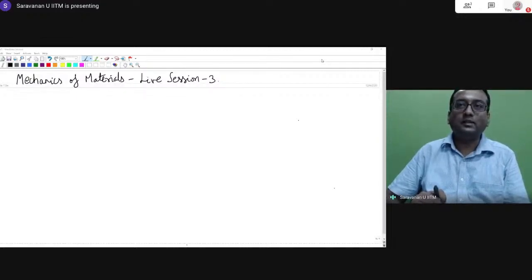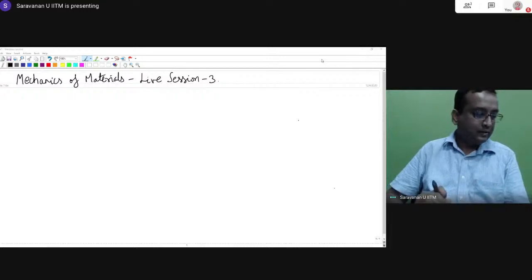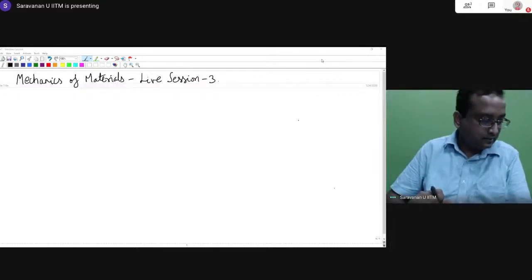Apart from this, there's no physical significance, unlike the determinant of the deformation gradient, which will give you the volume in the deformed configuration and things like that. So the determinant of the stress tensor just tells you whether the state of stress is three-dimensional or of a lesser dimension. That is the meaning of the determinant of the stress tensor.